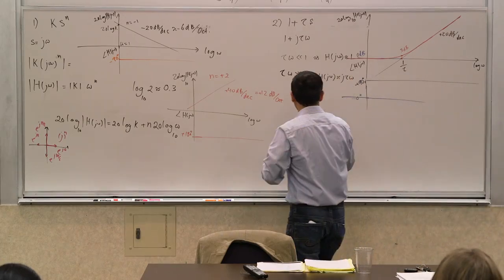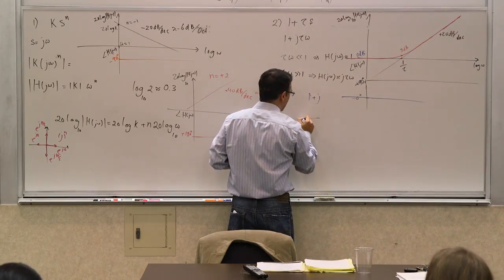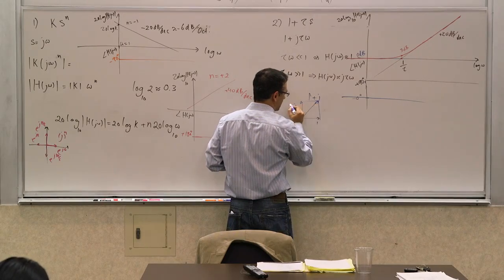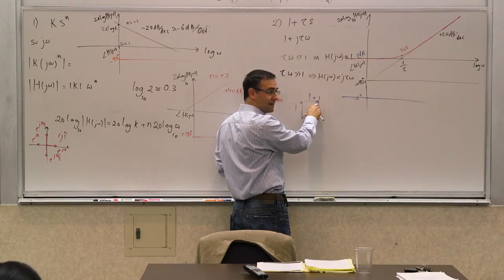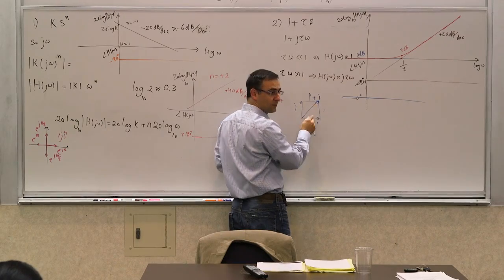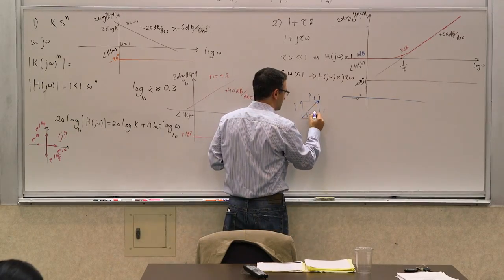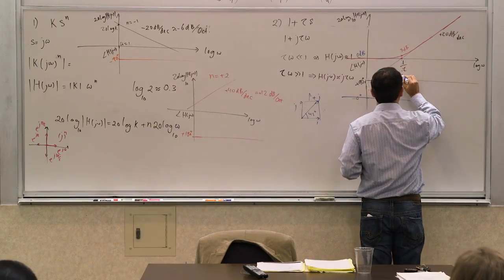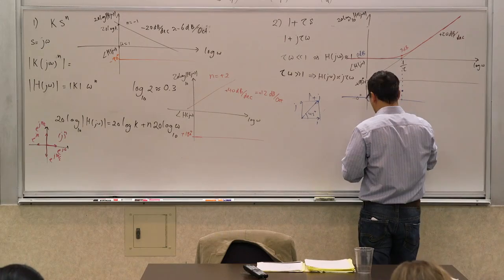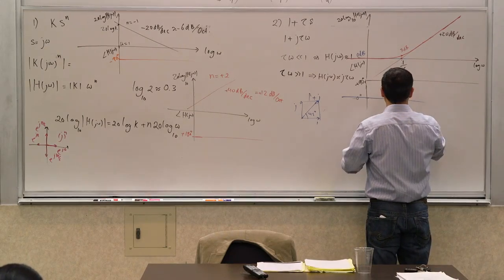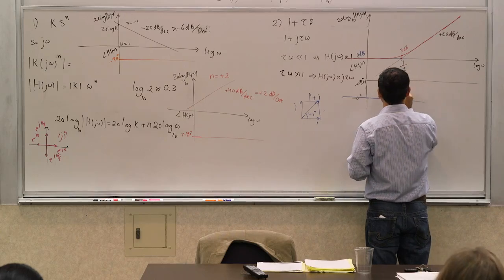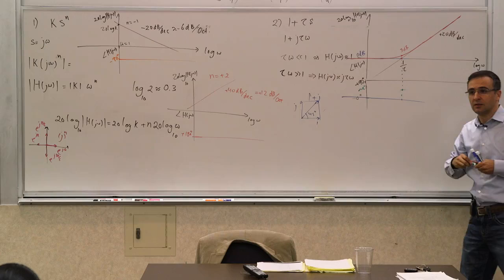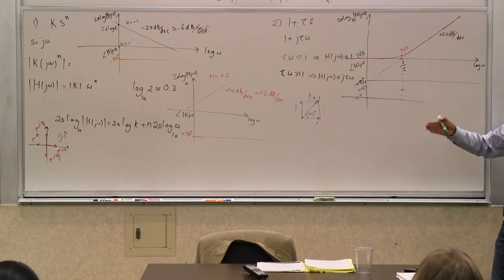If you think about it, it was 1 plus j at that frequency, so it's 2 vectors of equal magnitude. This has the magnitude of square root of 2, and this is 45 degrees. So at this frequency, I know exactly what it is. At this exact frequency, it's exactly halfway through. So my phase at this point is plus 45 degrees. So we know it transitioned from 0 degrees to 90 degrees, and it goes through that.